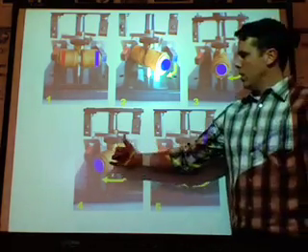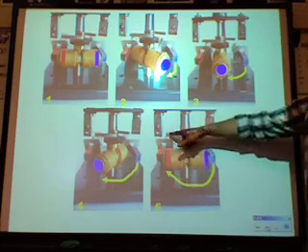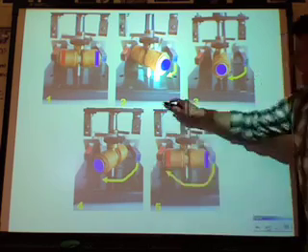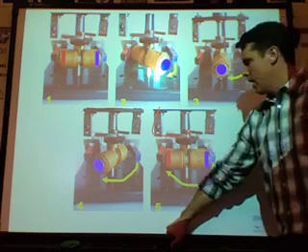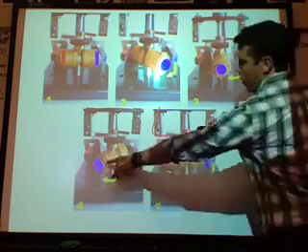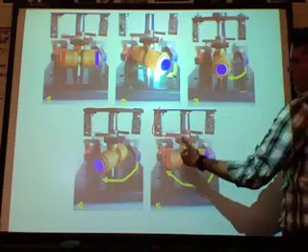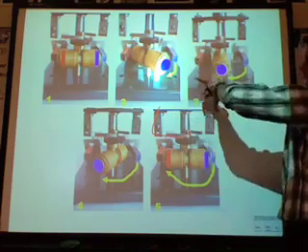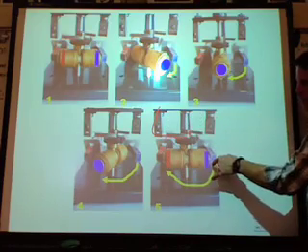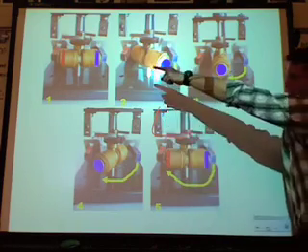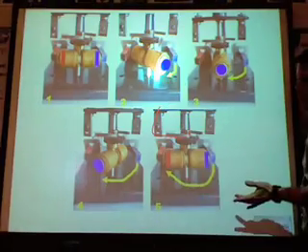Fortunately, though, when the coil gets halfway around, that happens to be the exact same time that this wire going to this side now connects to the other side of the ring. And what that does, you'll notice that my pole that was blue becomes red. The poles have switched. It's just like taking the wires off and switching the connections. We make now this end red and this end blue, and once again, we're like we were at the beginning in step one. We're repelling, and the motor continues to spin.